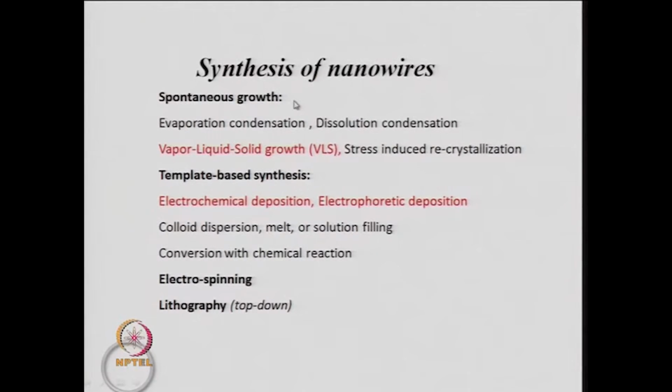One is the spontaneous growth methodology, which includes evaporation condensation, dissolution condensation, vapor liquid solid growth and stress induced recrystallization methods, and also CVD type of methods, out of which we discussed to a larger extent the vapor liquid solid growth, also called the VLS growth mechanism of making nanowires. These all form under the spontaneous growth of nanowires.